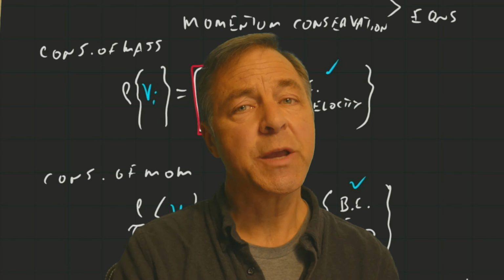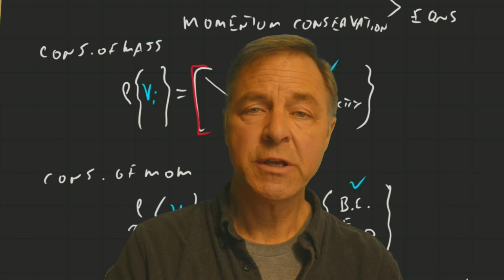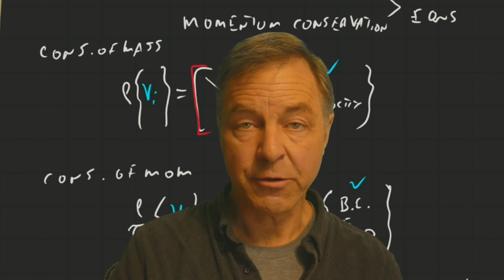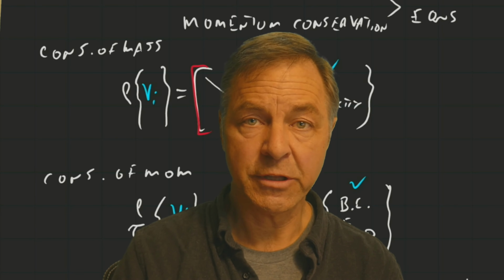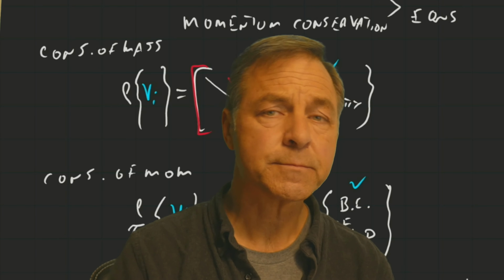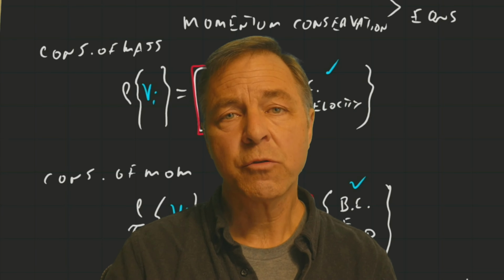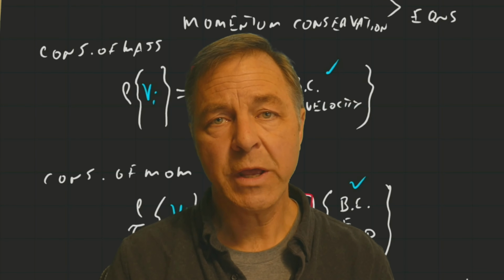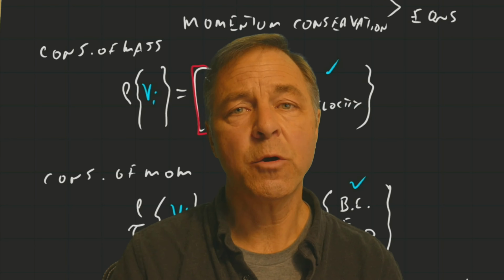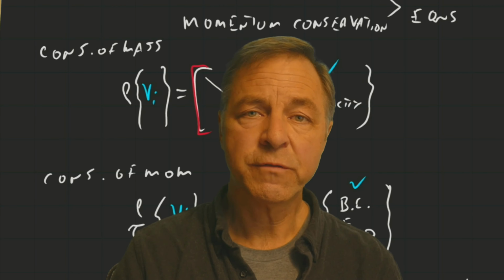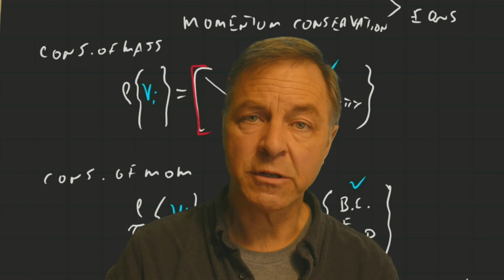And that's because we had another problem, which was the simulation calculation area. The volume we were doing the calculation in was too small. The streamlines that we were creating were crossing the boundaries in uncertain ways, and we really didn't know what the true flow field was, and that was affecting our result.